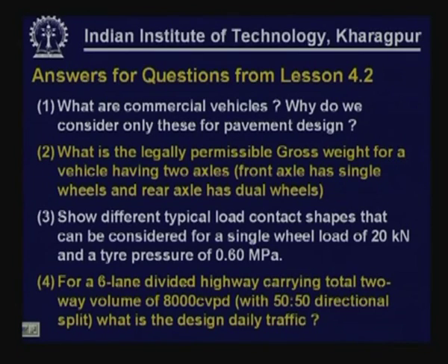Of course, we have to adjust this using the appropriate vehicle damage factor and then convert this into equivalent standard axle load repetitions. That in fact is the input that we are going to use for pavement design.